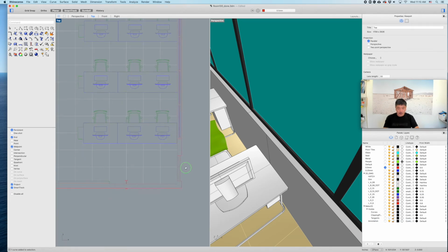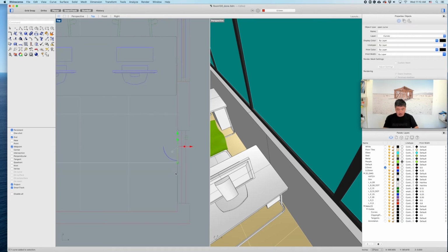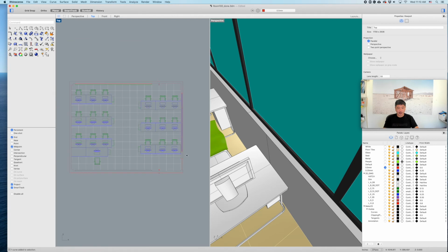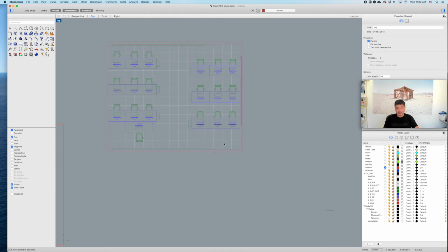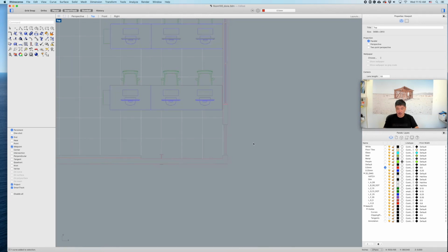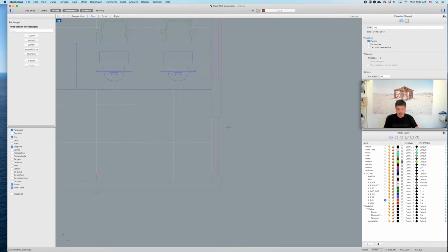And the door. So this line should be on the floor, so I think I'm going to change it to 0.08. And that door should be open, swinging to this side. Typically, when you have some kind of passage situation, you don't just construct a boundary between them. So what you do is activate line G 0.5 layer and then draw a box on the door.